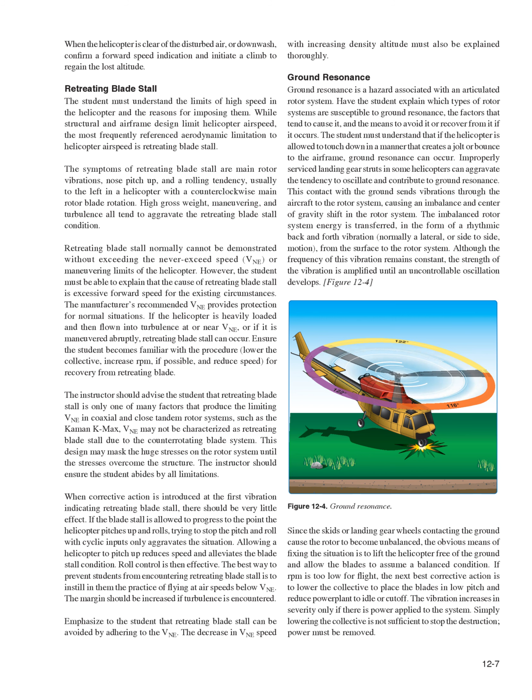If the helicopter is heavily loaded and then flown into turbulence at or near VNE, or if it is maneuvered abruptly, retreating blade stall can occur. Ensure the student becomes familiar with the procedure: lower the collective, increase RPM if possible, and reduce speed for recovery from retreating blade stall. The instructor should advise the student that retreating blade stall is only one of many factors that